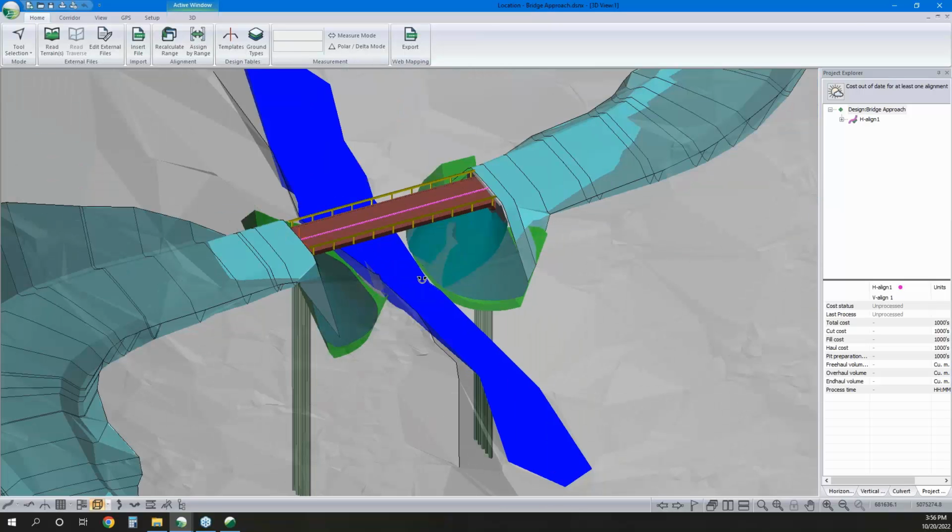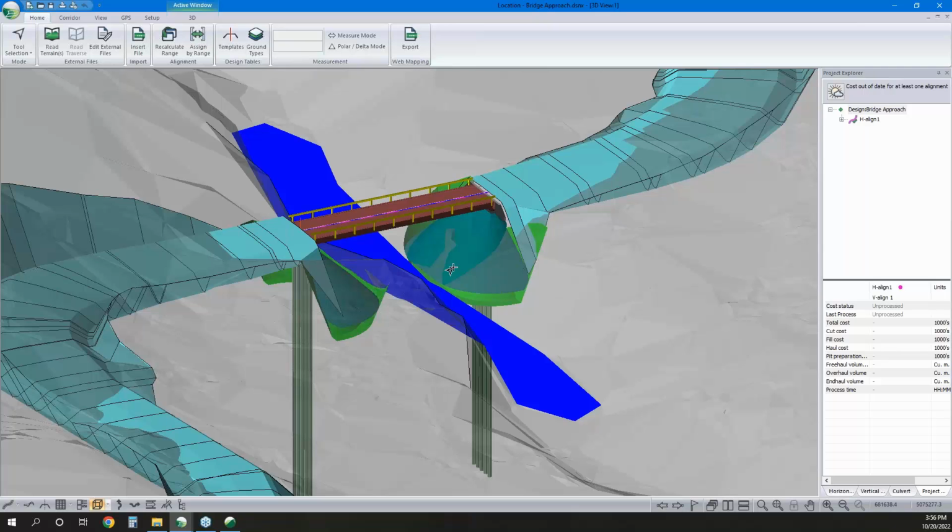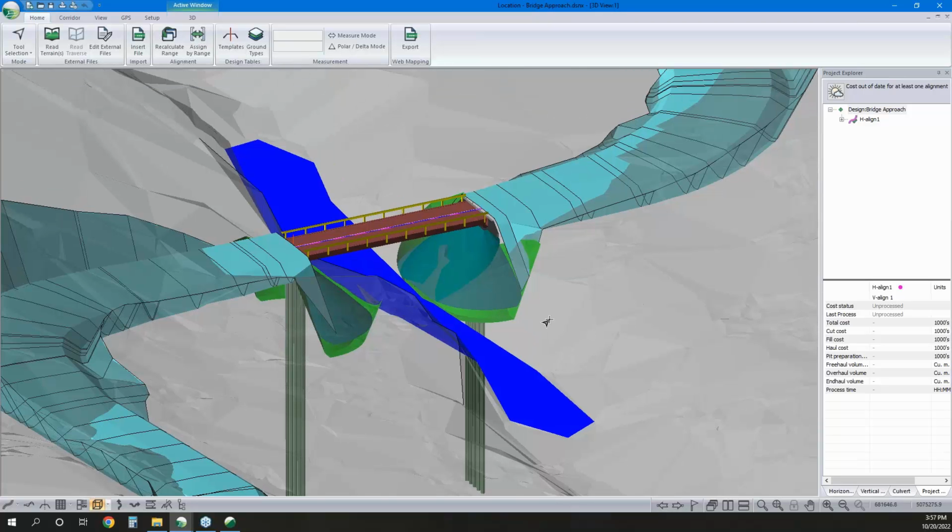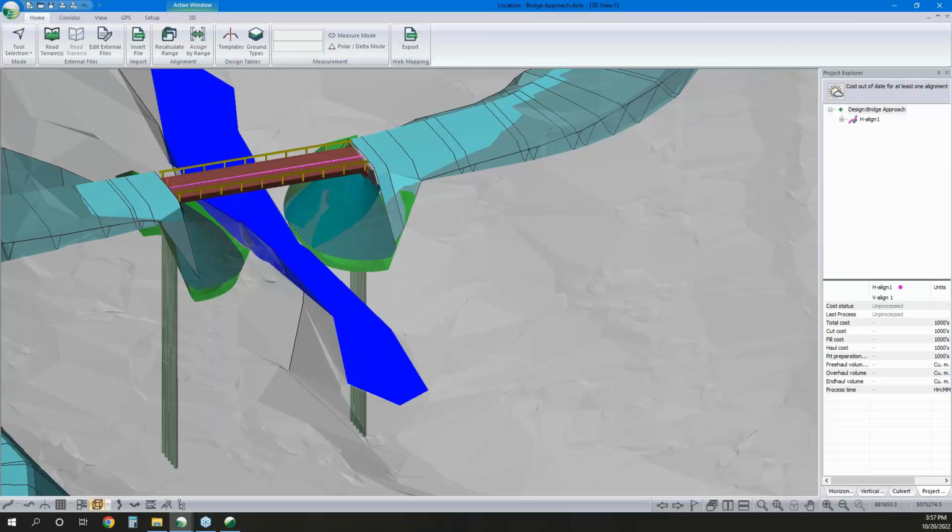But for our bridge abutments and figuring out how far out that armor is going to go, we do that modeling in terrain. So we define our superstructure, figure out where our sill is or wherever our armor is going to start, and then we'll grade down to either an elevation or a target surface to model our armoring and the abutment excavation.